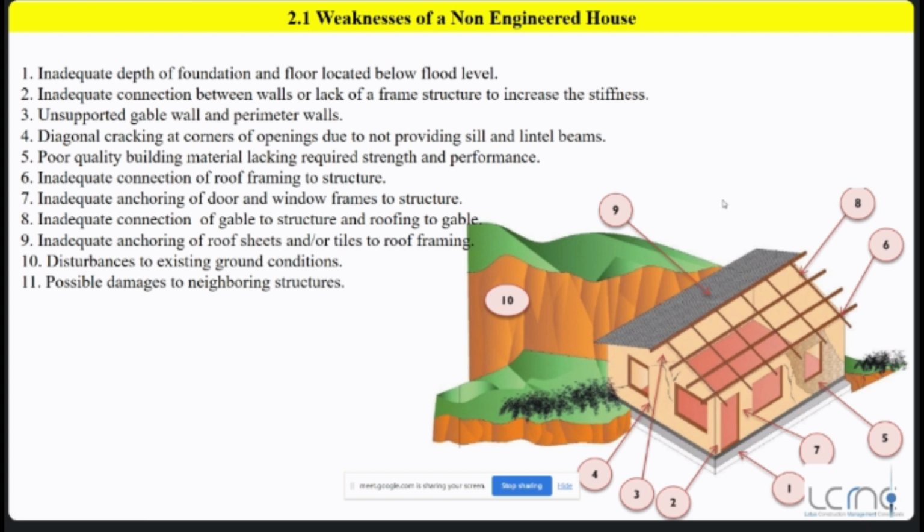So there must be an adequate connection to the existing structure for the roof structure. So we are using anchors to the wall. If you closely monitor the roof construction works, you can see how we fix these wall plates into the wall, how we fix these ridge boards, what the lapping is between the connections, what the rafter spacings are, and what the purlins are. You can have a clear idea when you observe closely. Okay, so that is that.